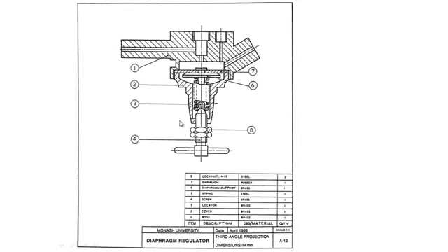So we might have a requirement where we want the distance between our two nuts to be 20 millimeters plus or minus a millimeter. Important to note that this is a dimension that is only required in the assembly drawing, because it's not something specific to a part, so it's not going to be in any of the detailed drawings. It's a dimension that we need to know just when we're putting our device together.